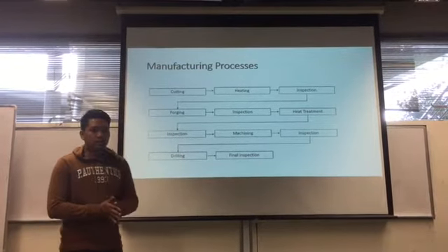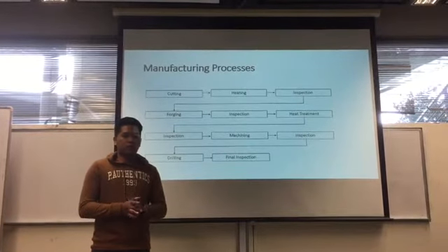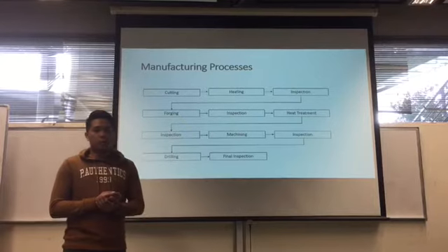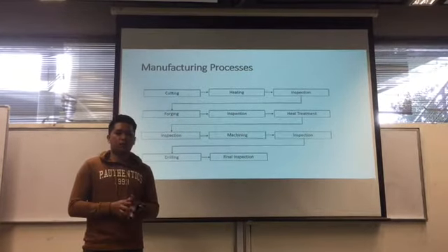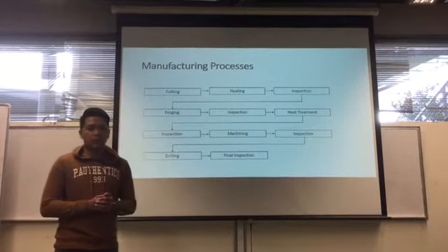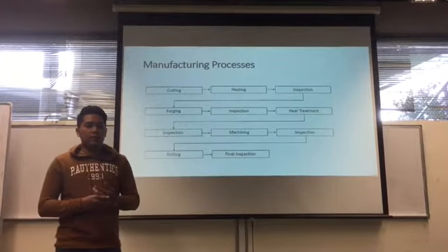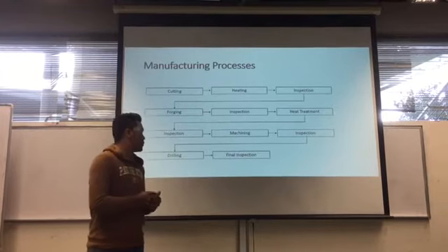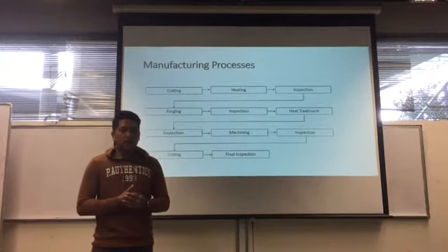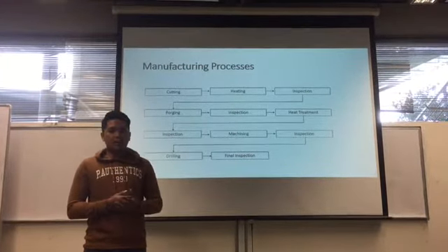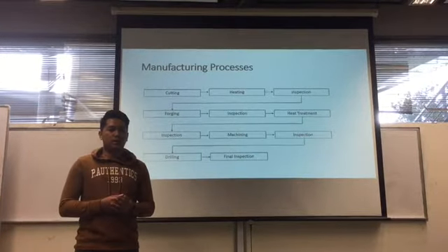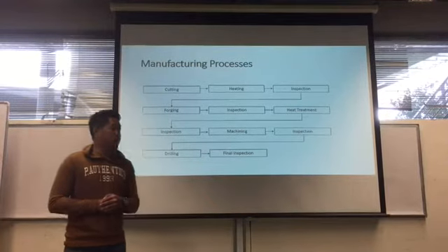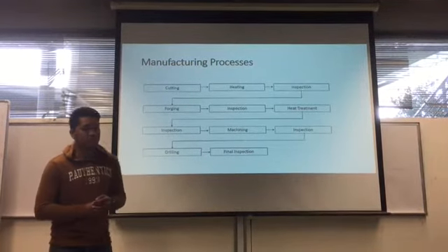and we will proceed with the heat treatment. The material that we have chosen for this flange is stainless steel 304, because stainless steel 304 cannot be hardened by heat treatment in general. It can only undergo annealing or solution treatment. That's why we choose stainless steel 304. And the solution treatment or annealing can be done by rapid cooling after heating to 1010 to 1120 degrees Celsius.